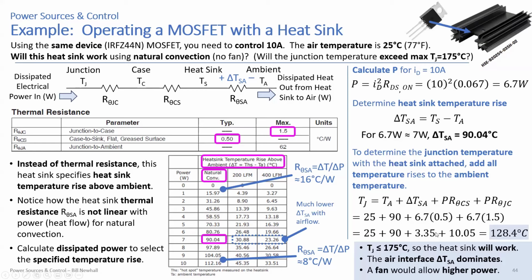Okay, so this is a basic analysis. If I were putting a few amps through a MOSFET, I would do this analysis. If I'm using more than an amp through a MOSFET I'm controlling, I'd think, do I have to hook this to the case? By that, I mean the product case or the prototype case. Do I have to use a heat sink? Do I need a fan? So you would go through this analysis just to get an idea, are you close to the limits? If you're not close to the limits, I'd probably stop here after a sanity check, maybe a measurement. And then if you're really close to the limits, then you really have to go into some more detailed thermal analysis, get your thermal engineer involved using some better modeling tools.